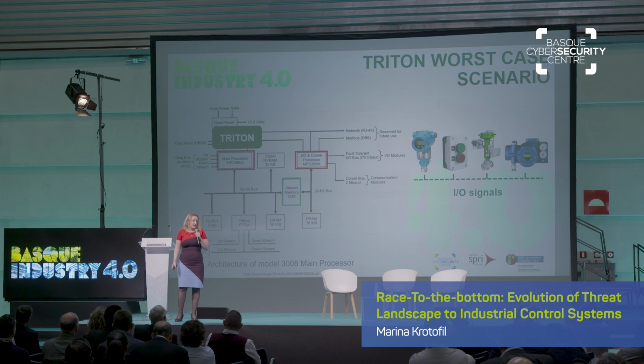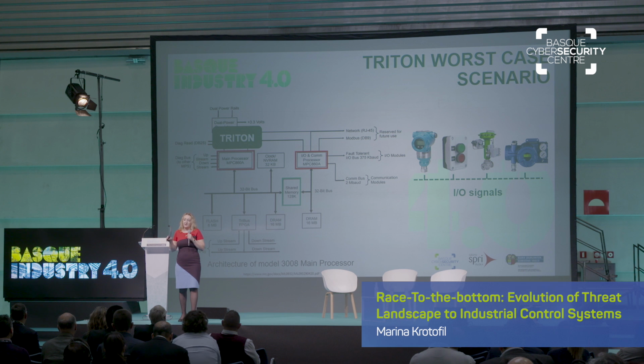So what is the Triton worst case? What would it be like if the attacker successfully injected the implant? This is the electronic board of the safety controller. The safety controller is designed so that the main processor of the controller and the communication processor are located on the same electronic board, and they communicate with each other via shared memory. So with literally a couple of lines of code, the attacker can already write any command to the input-output card. He can basically manipulate final elements like valves at will.